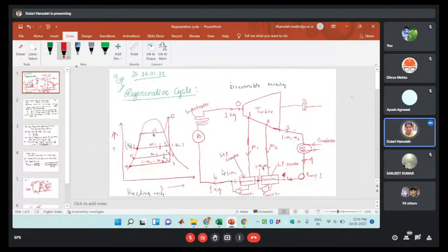कंडीशन यहाँ पे सेम है, यहाँ पे कुछ भी नहीं हो रहा है, सिर्फ पंप करके यहाँ पे हीट एक्सचेंजर को वो दे रहा है। कंडीशन यहाँ पे और यहाँ पे सेम है। तो मैम 4 लेंगे ना, फिर 3 तो नहीं लेंगे ना? नहीं, 4 लेंगे क्योंकि ये जो पॉइंट है, यहाँ पे इनलेट टू द कंडीशन, और ये हम हीट बैलेंस में लेंगे। ये हीटर है, देखिए यहाँ पे हीट एक्सचेंज हुआ ना, यहाँ पे तो हीट एक्सचेंज नहीं हो रही है, ये सिर्फ प्रेशर में जितना स्टीम का प्रेशर है, उसको दे दिया।